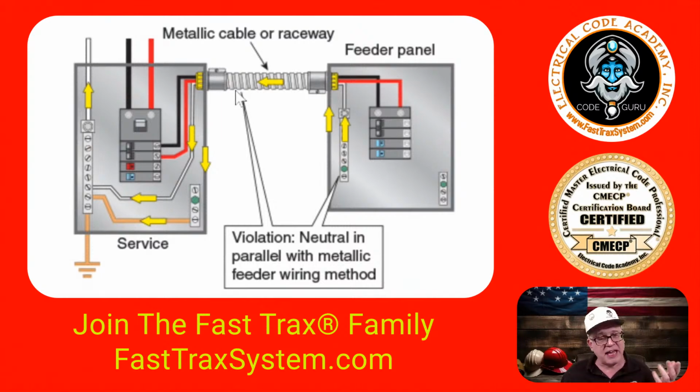This is not MC cable because I see no separate equipment grounding conductor, and you can't use the MC armor as an equipment ground in larger sizes. You can in specially made MC with 6-gauge conductors and less, but that's not what this is.